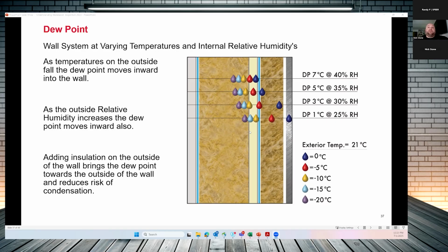Now, if you were to think about this from a foam perspective, one of the big issues that we run into is that over time the buildings rack. As the buildings dry out, they shrink. The framing itself will shrink a little bit, which has potential to pull away from some of those foam areas. Maybe some of the foam starts to off gas and shrink a little bit as well. So you start to get these areas around the frame that could potentially see some connectivity to the outside shell, causing some moisture related issues.